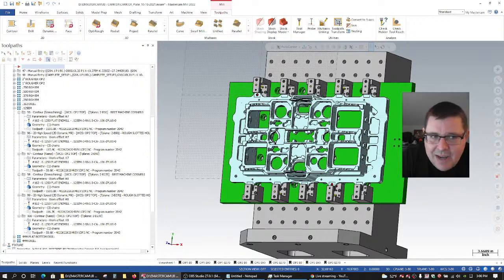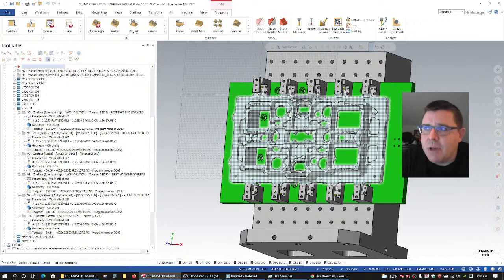Now, you may not have noticed much of a change when I make that first change. Say something this size or bigger. This is a pretty big model, but generally I'm talking about stuff that's bigger. So for something this big, a 1/1000 chord height, so here's what it really comes down to. How long does it take to shade your model? If it takes like half a second, that's probably okay. It's probably acceptable. If it takes you 10 seconds to shade or unshade the model, that's when we really want